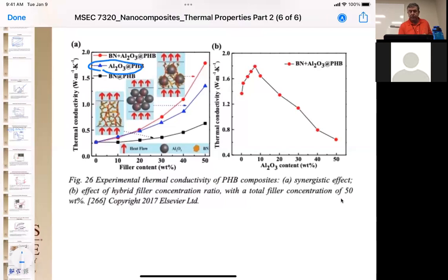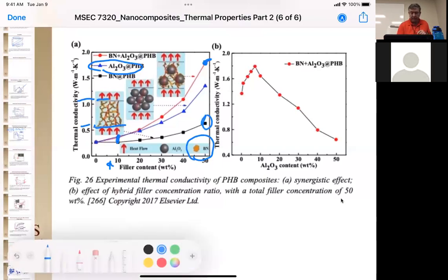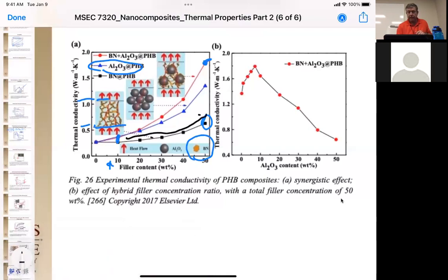Okay, so if we have just the boron nitride platelets, the hexagonal boron nitride platelets, when they form a matrix here, we can get a nice thermal conductivity going through here in this range, okay, at a decent loading factor. Notice this loading factor is 10% right here. And so we get a decent effect here. And so this is the one with the boron nitride by itself, in black on the bottom, right here. And it has the platelets. The platelets have to kind of arrange. You'd think that they'd have a better thermal conductivity, but it doesn't.